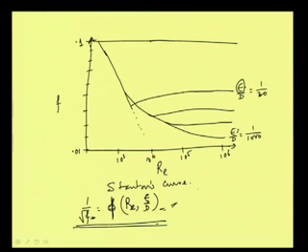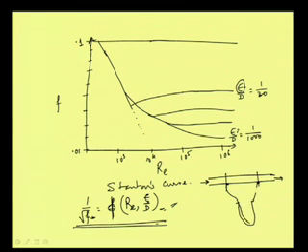That sort of experimentation is not that difficult. Say we can fix the pipe, and we can allow the water to flow from here to here, and then from these 2 points, suppose any 2 sections, we can fix a manometer, and using that manometer we can see the difference in the pressure level, mercury level here, and then from that we can find out what the head loss is.